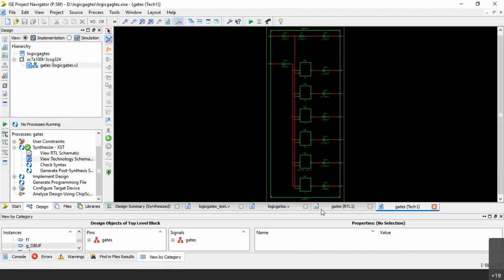Now, for this circuit diagram, the Xilinx tool itself will give one more file called netlist file. In the netlist file, it will mention all these LUT2 instances, D1, E1, F1. All that LUT is already present inside the library, and all these buffers are by default present in the library, and all the nodes are connected by means of wires here.